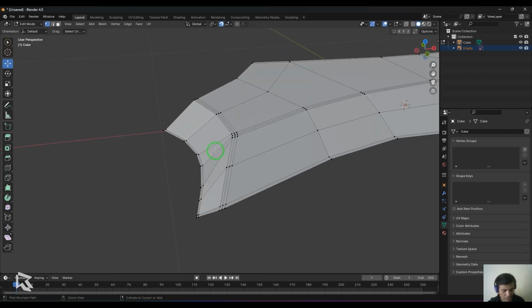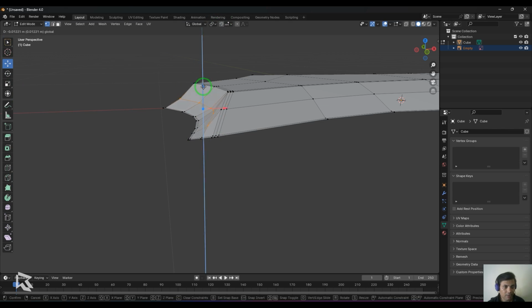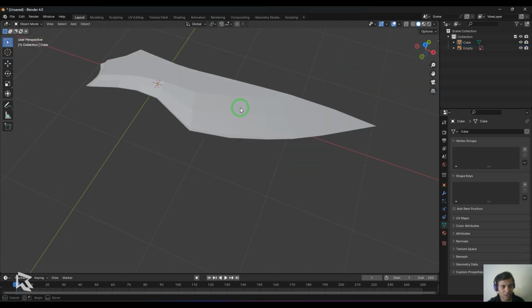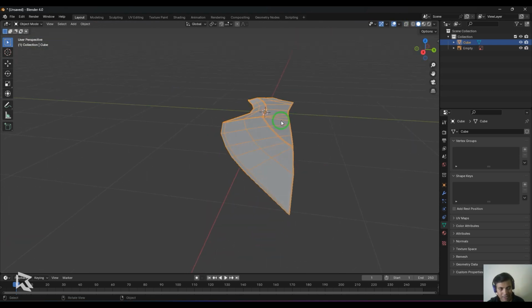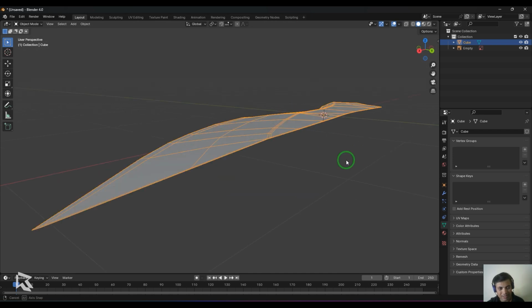I press Ctrl R, add those lines, and then select those lines there, and then slightly move it inside. So I just switch off the snap option and then just dip those points like that. So you should be able to see now I've got this blade here with some thickness in the middle and gradually sloping down here. You could see it's gradually becoming thin.